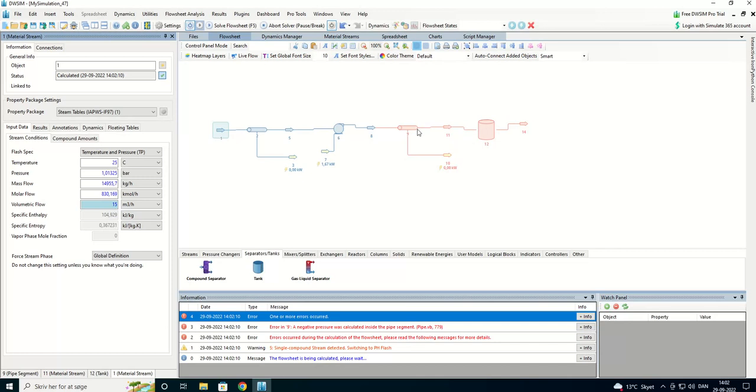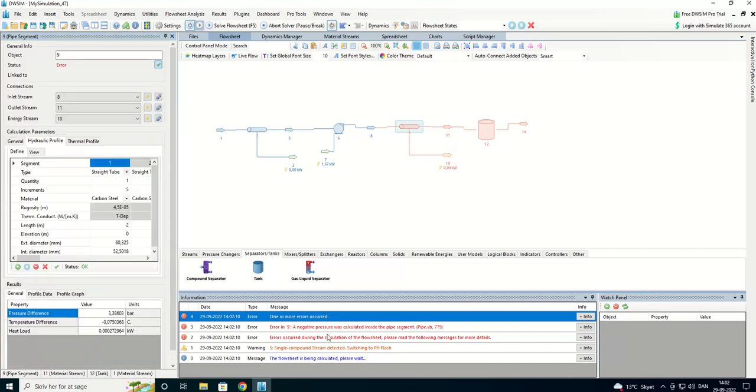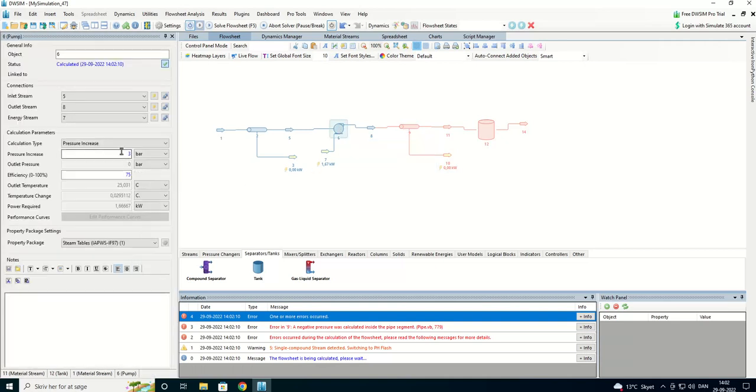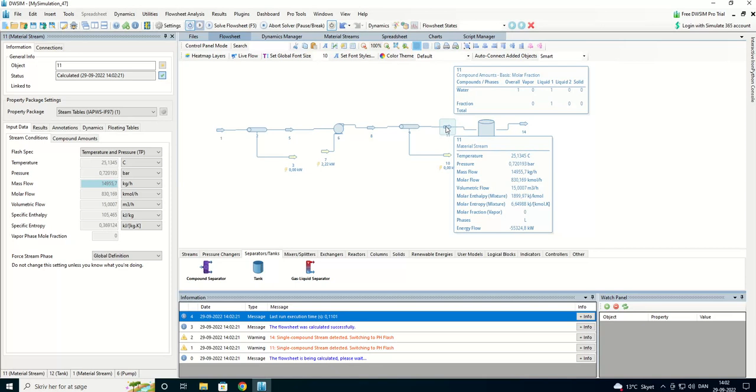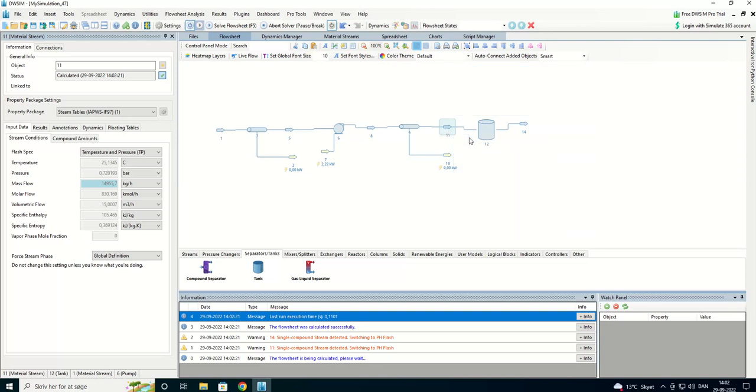So now it went red here again. Okay, negative pressure. The 3 bars wasn't enough. We can try with 4. Okay, 4 is enough. Quite enough. It only used 0.72 bar, and we know if we're going into an open tank, it has atmospheric pressure.